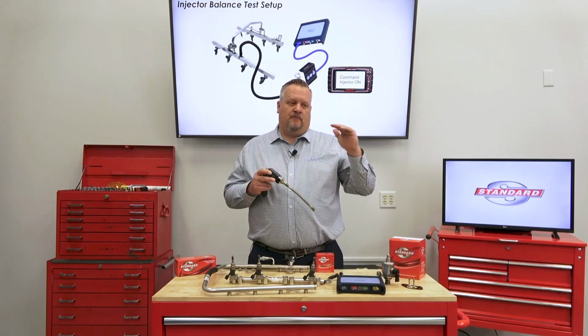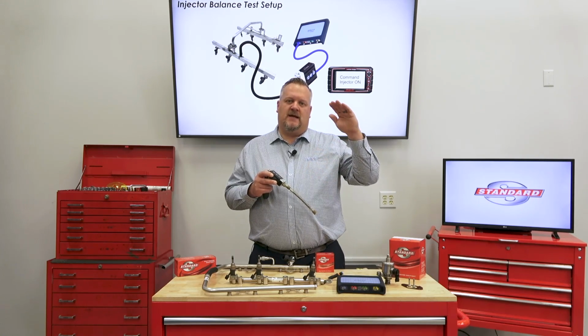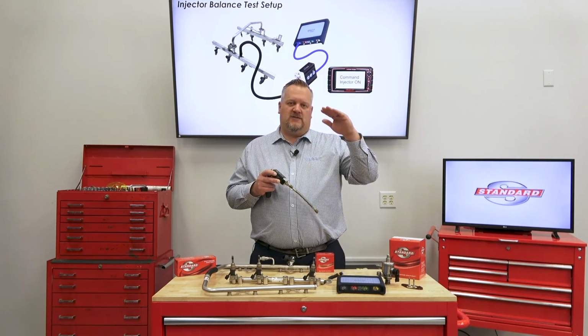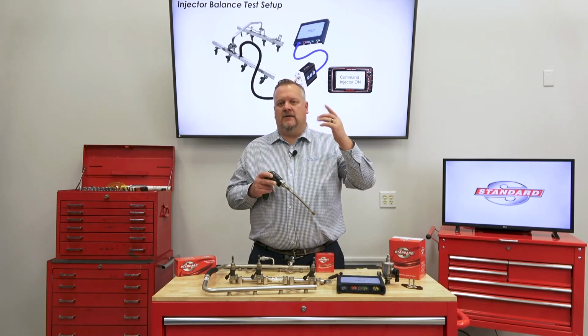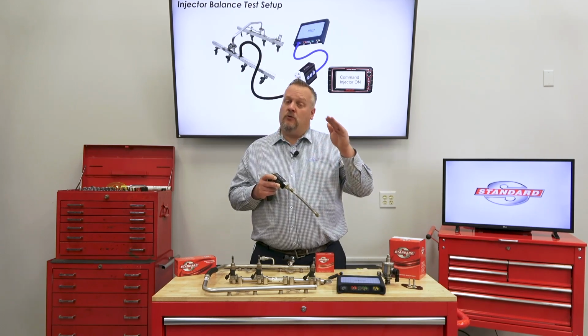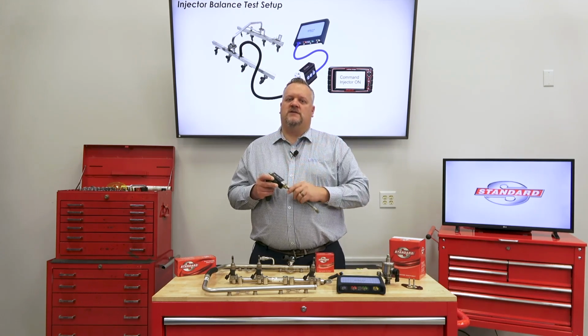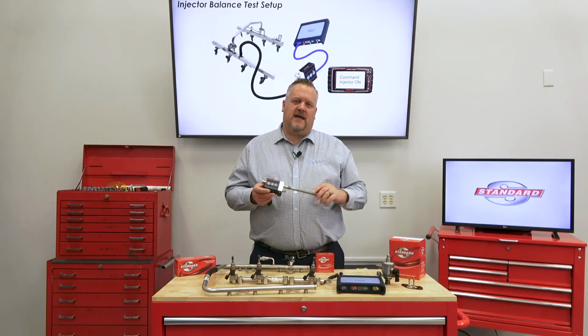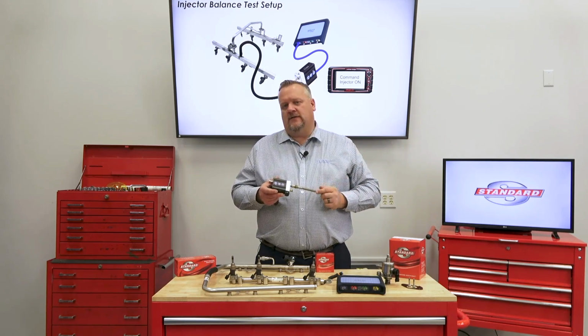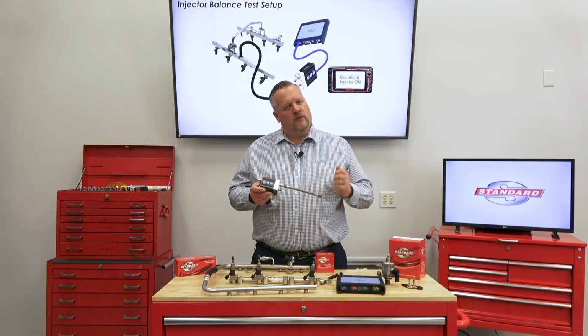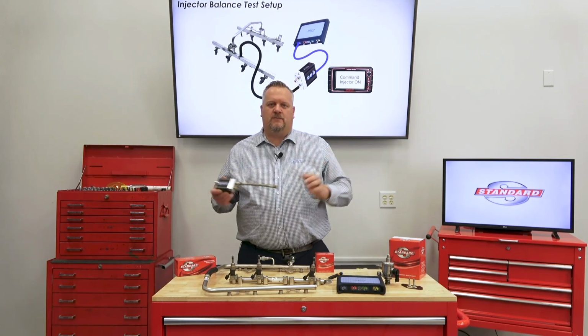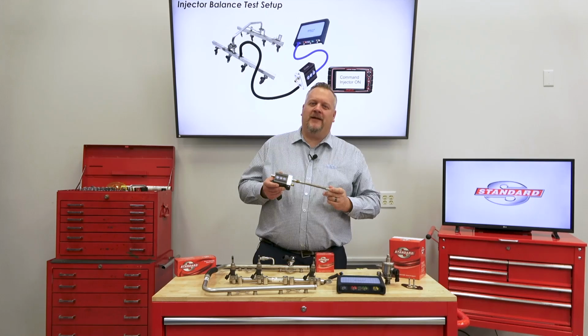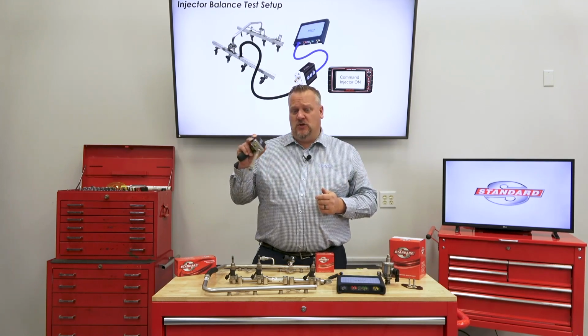And so it's going to power up the fuel pump, it's going to cycle each injector a certain amount of times, and you, the technician, need to observe and record the amount of fuel pressure that's being dropped. Some people might not necessarily like this test because, again, it's a relatively static test. Sitting in the bay, we're not really stressing out, but where was this fault happening? That's right, it was happening at idle. So this technician used this.